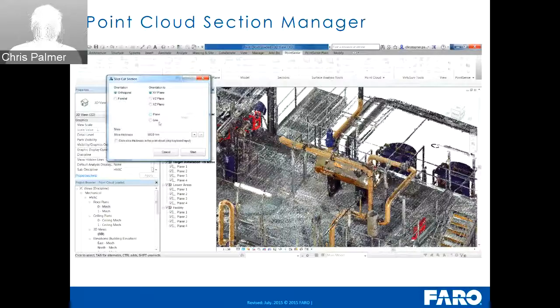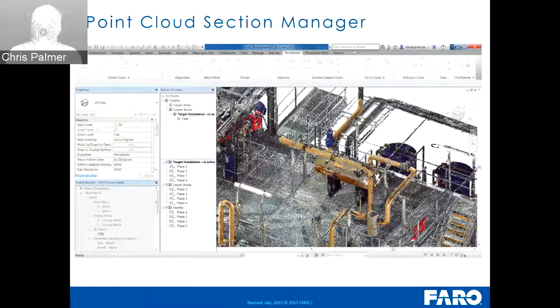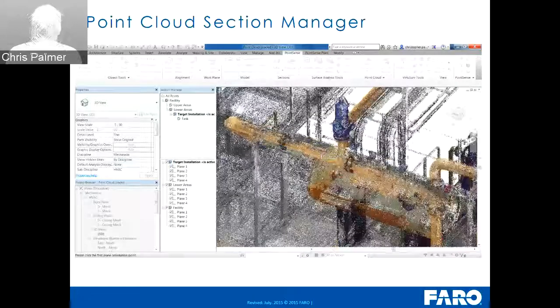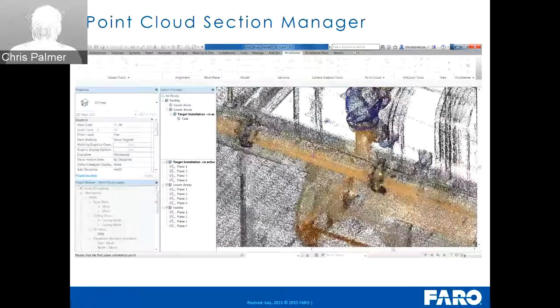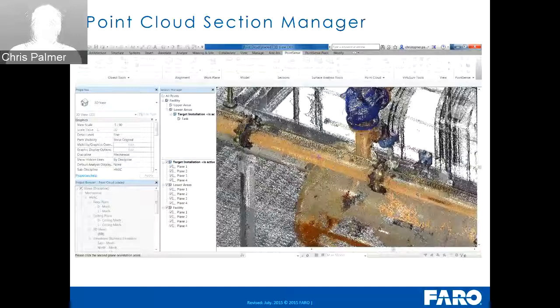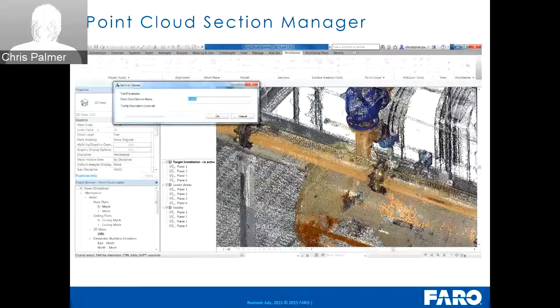But if we maybe go for a 500mm slice, orthogonal to the X and Y plane, we just zoom in on a specific pipe here. I literally just need to give this 1 click, and that's going to define a plane orthogonal to the X and Y. So we'll call this, just for reference, orthogonal 500mm slice, and we should probably say against the XY, so 2XY.